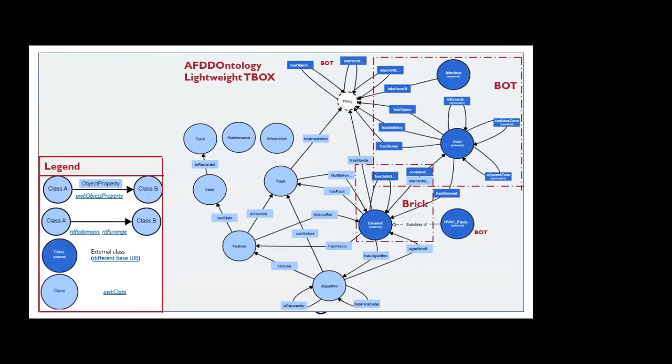And again, I'm using another ontology, as you mentioned, for the operation stage, which is Brick schema, that looks specifically at the HVAC system. It captures all the relationships of those. And I have created a mapping between BOT and Brick, where Element is a subclass of the HVAC equipment that relates to the BIM portion of it. So basically, I'm using BOT for the concepts that already exist in BIM, and Brick schema for the ones that come from BMS, and whatever is missing is introduced to the ontology.